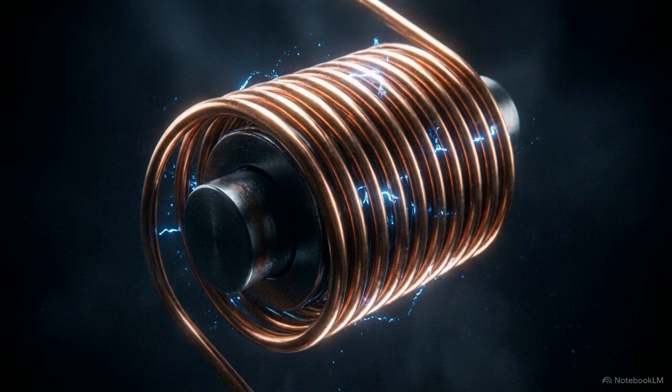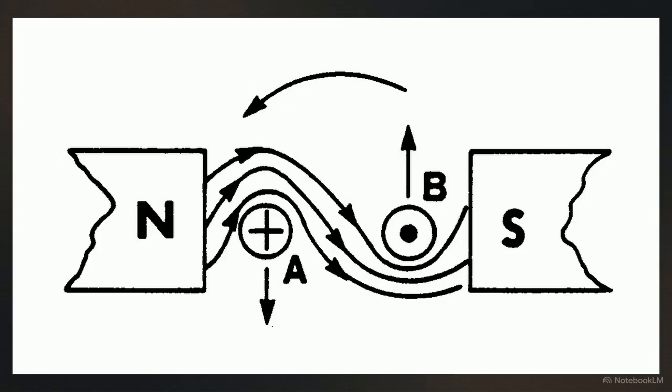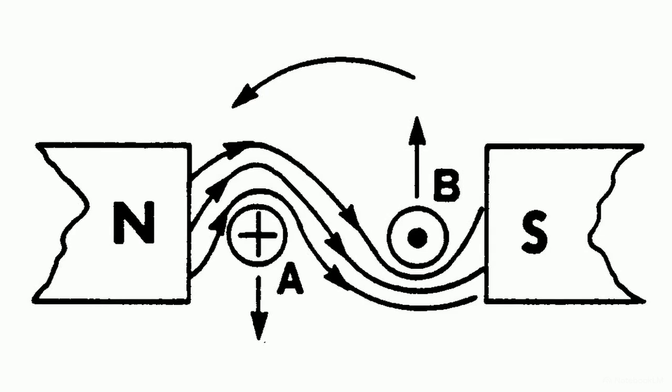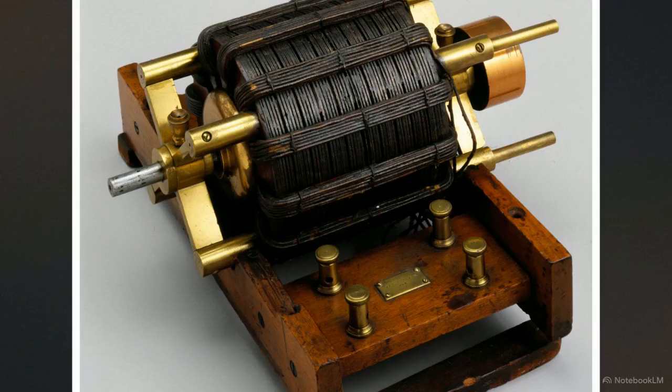Wrapping these coils around a metal bar concentrates the magnetic flux, creating an electromagnet capable of reacting to other magnetic fields with immense force. This cross-section demonstrates how we harness this interaction. A current-carrying wire loop between stationary magnetic poles causes the field lines to bend and distort. This creates a physical push and pull. Side A is thrust downwards and side B upwards, forcing the loop to turn. This continuous rotational action provides the foundational principle behind every electric motor in existence.